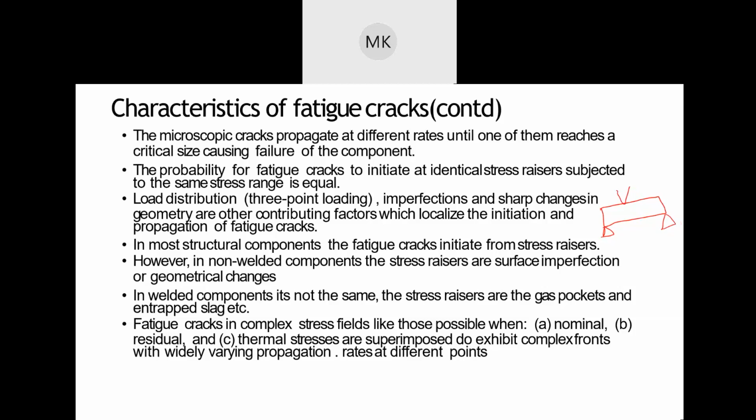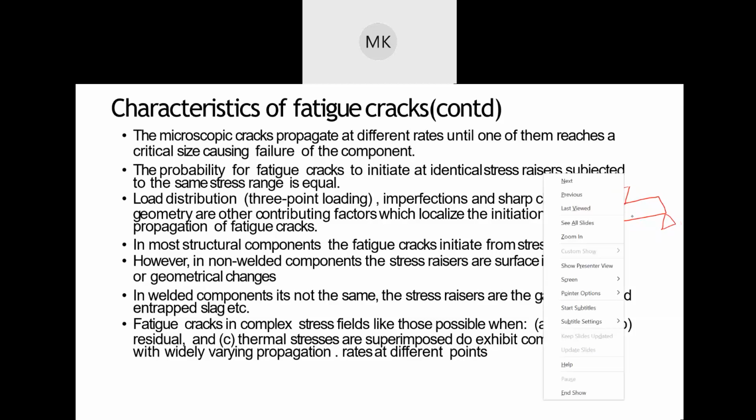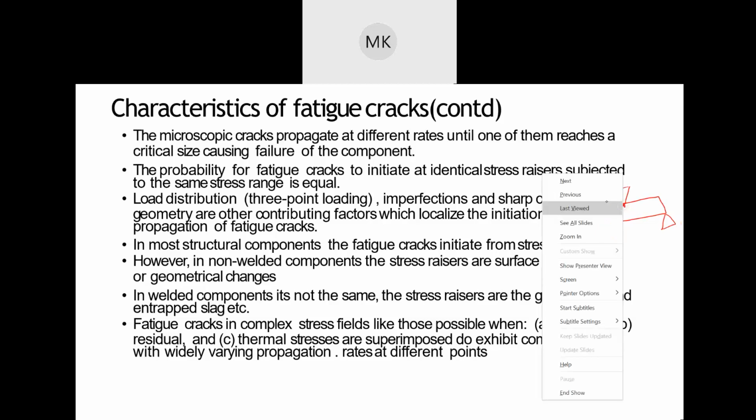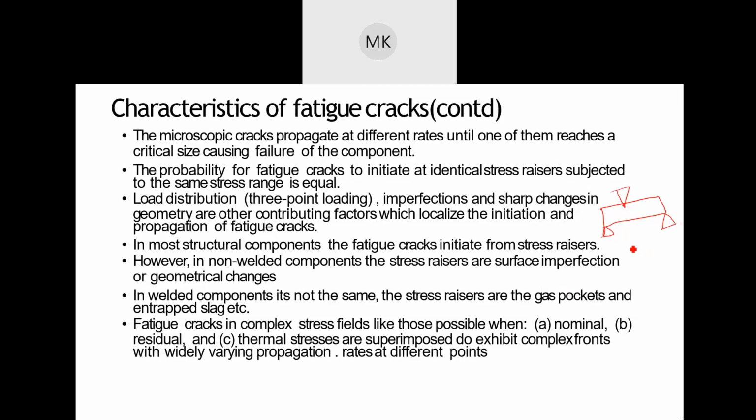What is the issue with this is in this kind of testing it is a little different because you are actually forcing or applying a load at a single point and making deformation start at that point over here. And since that area of contact is very low and the load that you're applying is higher, plastic deformation starts happening at that region.